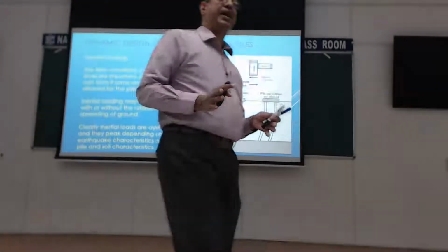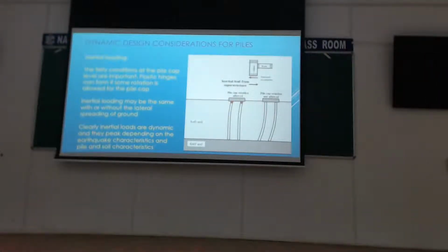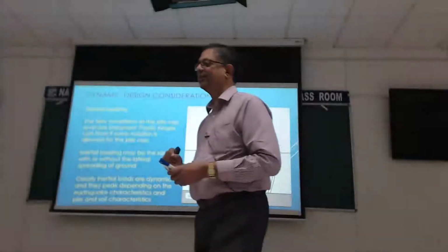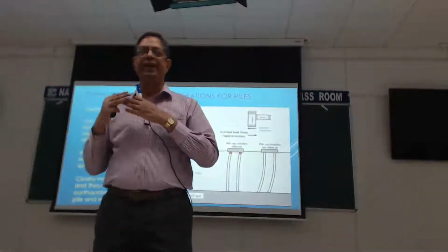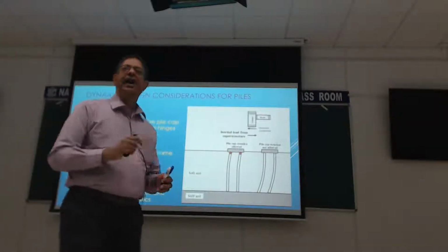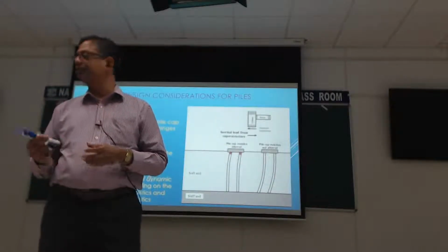Now, the failure mechanism immediately depends on how good your connection is between the pile cap and the piles. So, if you're a good structural engineer and carried the pile cap reinforcement properly to the piles and vice versa, it acts as one unit. That's good. On the other hand, if you chipped out on the connection, then of course you're asking for trouble.